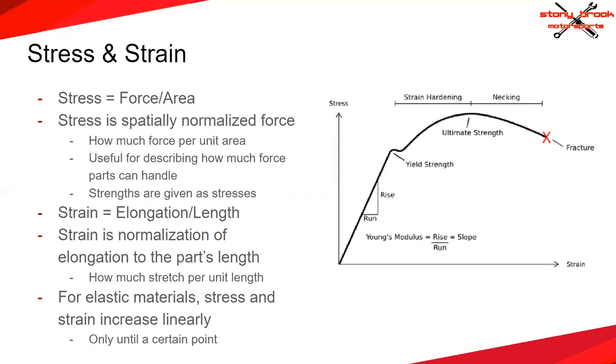Let's change the first thing to a meter. Say it's a meter, that thing is only stretching by 0.1%, whereas if it's a centimeter, it's stretching by 10%. That's a really huge difference, and it's important to know that. Essentially, also, if you take your strain and multiply it by 100%, you get the percent by which the part is stretching.